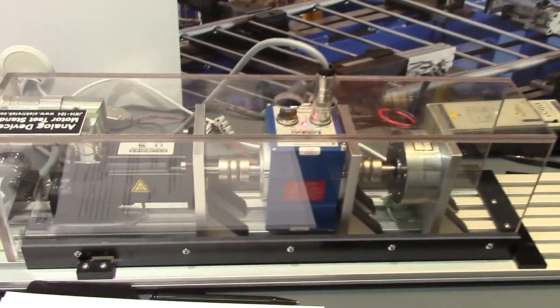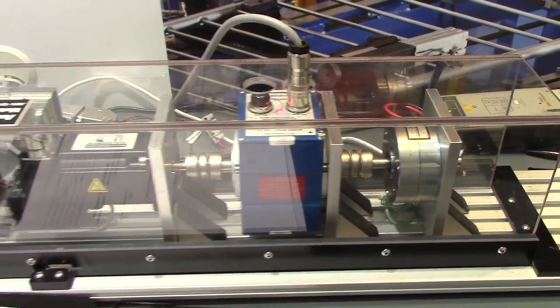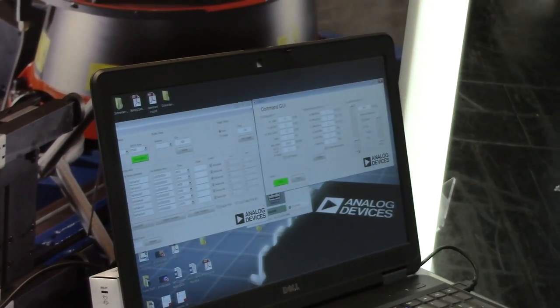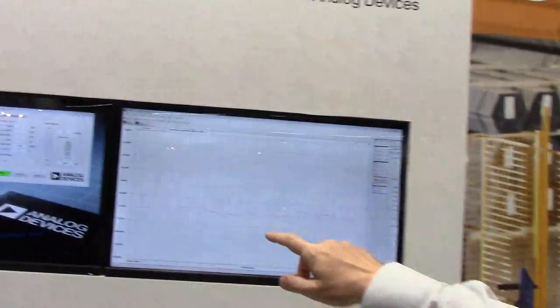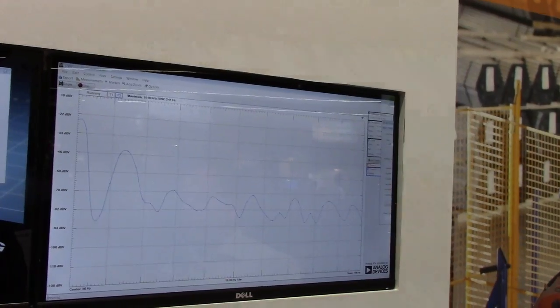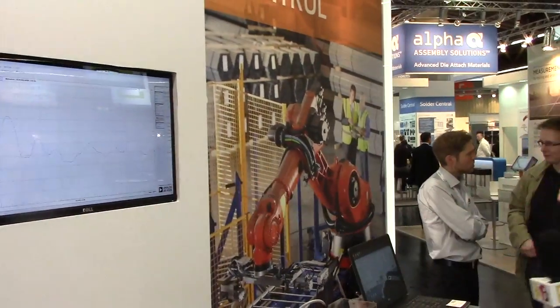So I'm running this motor here at about 800 RPM. So at the moment we're seeing a curve here that has the fundamental. This is a ripple component due to the mechanical setup. So it's a twice per revolution frequency. And then there's not so much ripple, there are much lower components then at the higher frequencies.